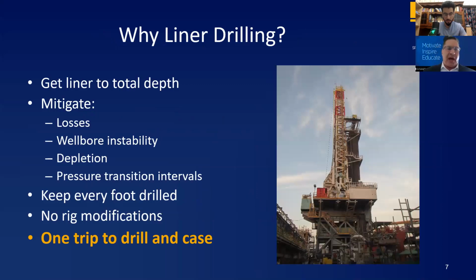I'm going to spend some time on this slide. Why would you want to liner drill? Get your liner to total depth or planned depth. For mitigating losses. Most of the liner drilling we do is mitigating lost circulation or depletion.